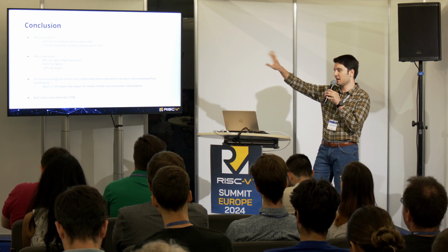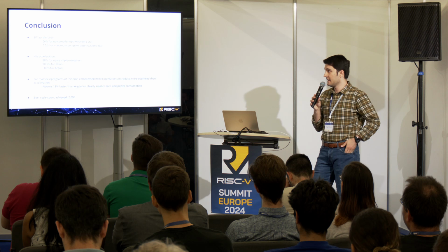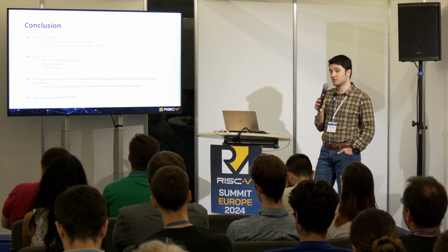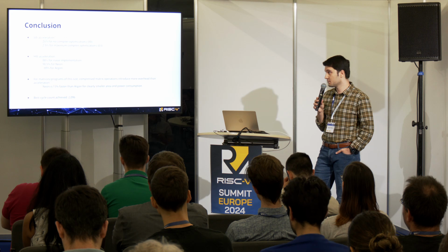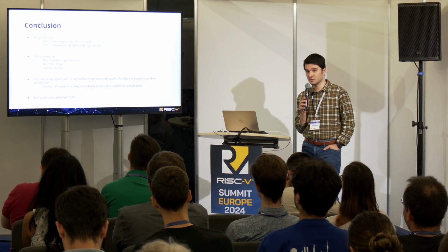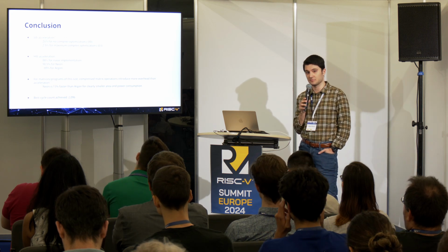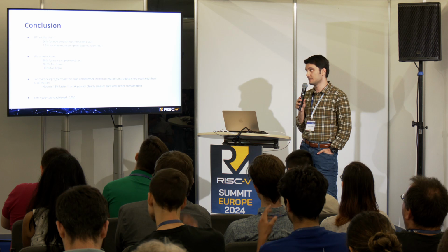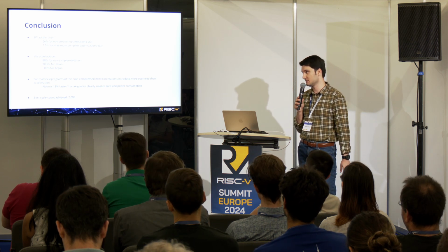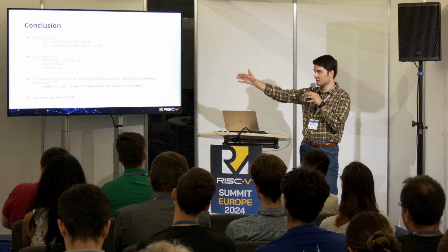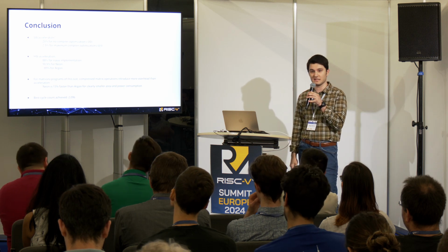This is not the final improvement. 88% for the naive implementation by introducing those 8 custom instructions. 90.5% for the version without compressed matrix multiplication. And 89% for the version with compressed matrix operations. And the best cycle count I got at the end was 2096.